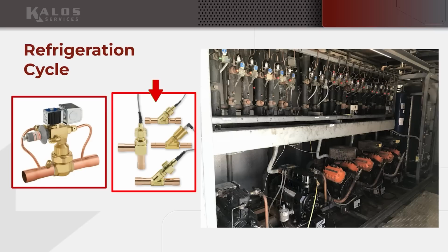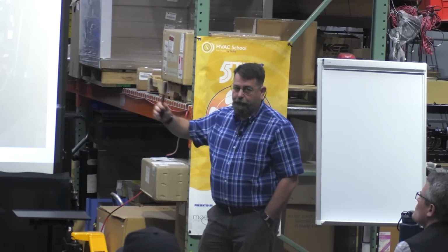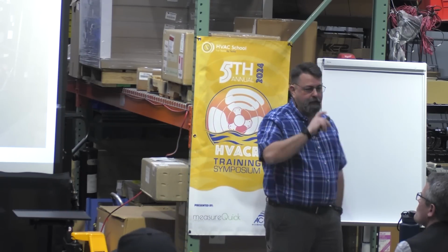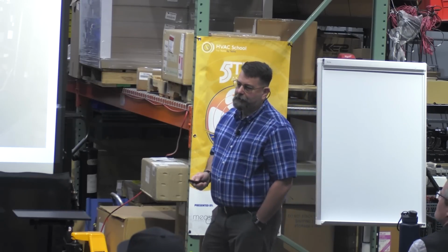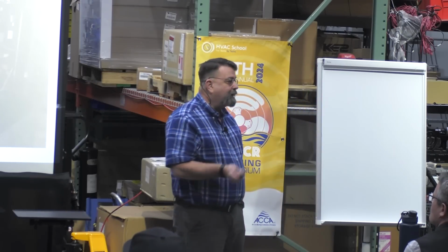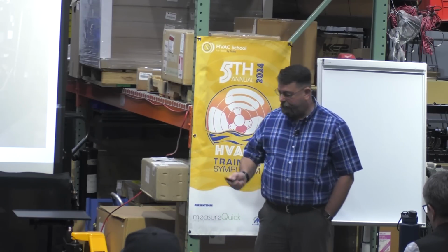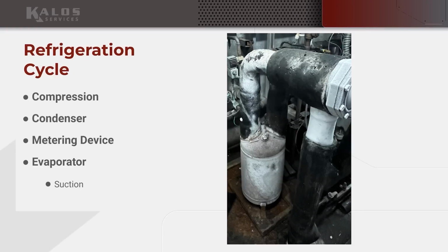That's without a doubt where we're going, right? The control is far better. The pressure drop across it, the loss of efficiency is far better. Everybody is going to eventually end up electronic, but there's so many out there. You know, the mechanical valves are going to be around for a long, long time. And anything new going in today is going to have electronic valves driving it. All right, so here's another piece.